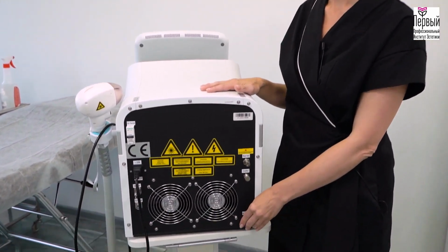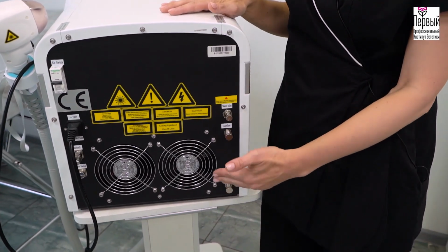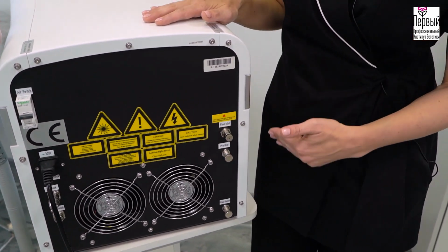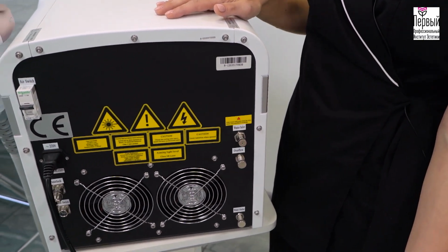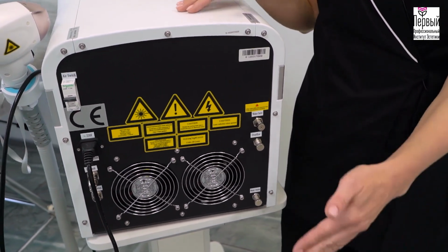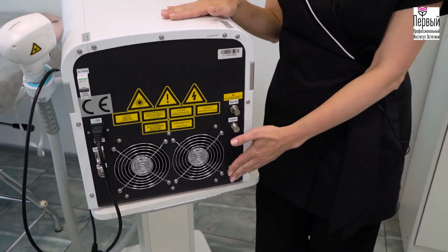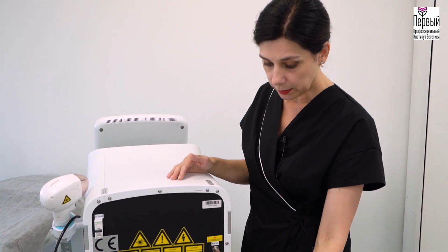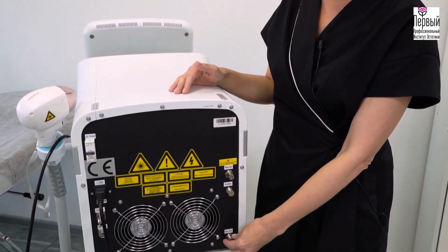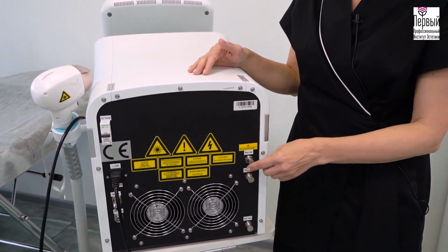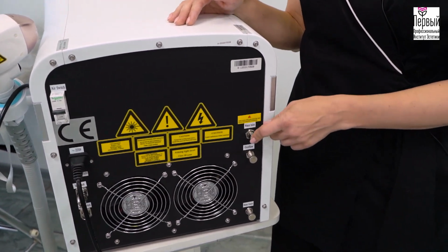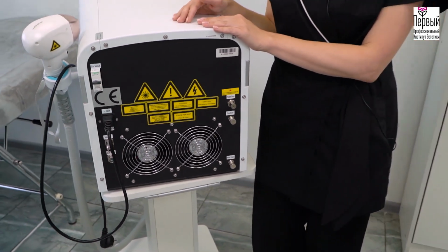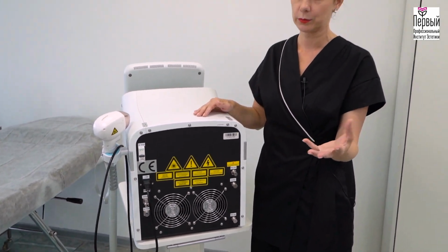We open the valve and insert the hose with the funnel. We open the air relief valve so that the air can start entering the system and the water will drain. Please use a basket. The amount of refilling water must be the same as the drained amount. Once the water stops draining, we close both valves and open the third one. Move the hose, lift the funnel up and fill the system with water until it starts to drain and bubble.